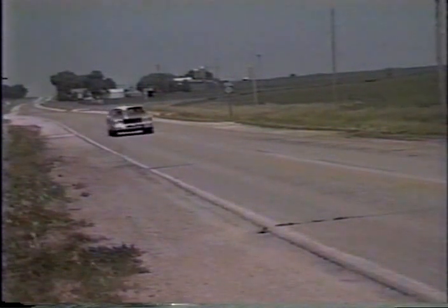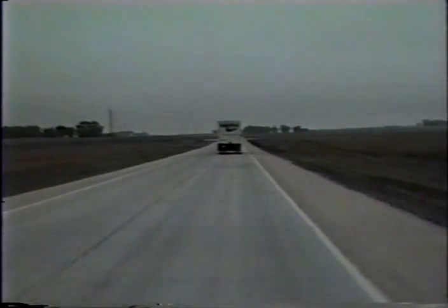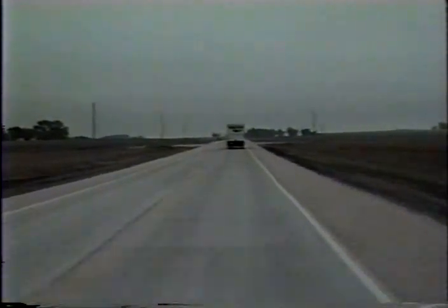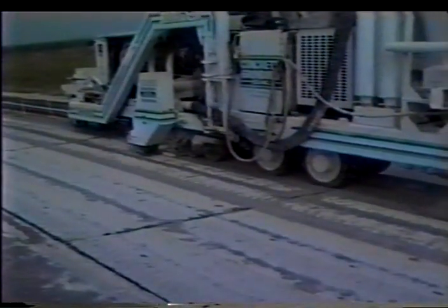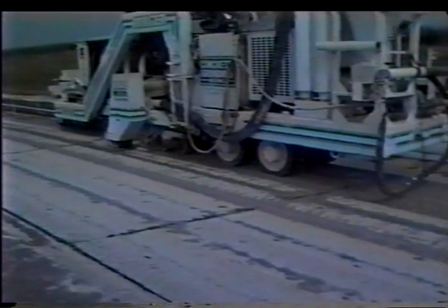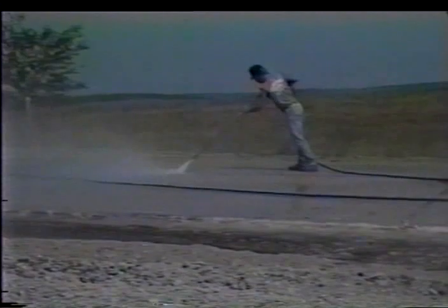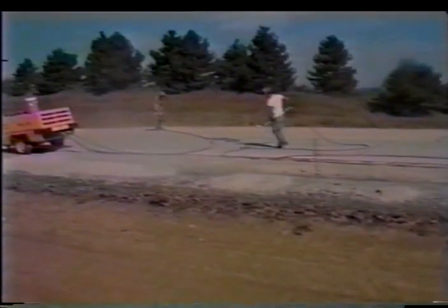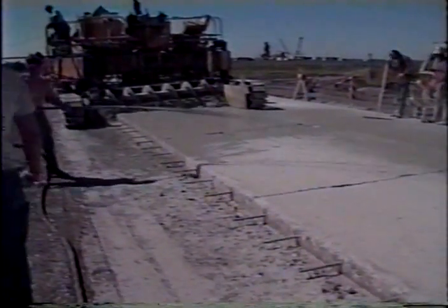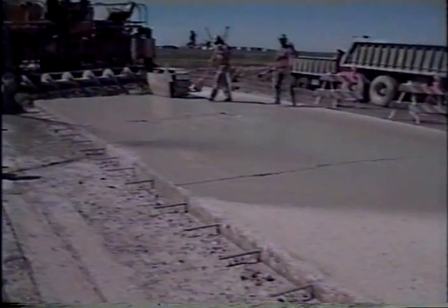A bonded concrete overlay is placed on a concrete pavement in relatively good condition. Its purpose is to increase the structural integrity of the existing pavement. Specific steps are taken to ensure that the overlay bonds to the existing pavement to form a monolithic structure. The existing pavement should first be thoroughly cleaned, or its surface prepared by an approved method, so that an adequate bond may be achieved. Most agencies then apply a bonding grout to the pavement surface just before placing the overlay to enhance the bonding between the two surfaces.